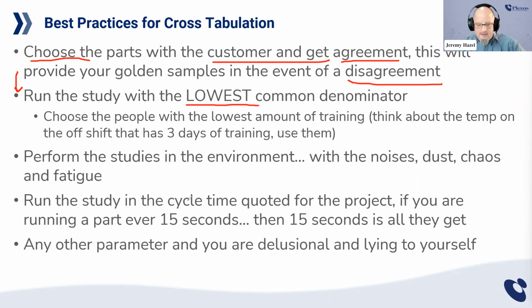The third thing, perform the studies in the exact same environment. Noise, dust, chaos, and this is a big one for me, fatigue. When I do my MSA studies, I grab my operators that will be doing it, again, with the lowest common denominator, toward the end of the shift after they are already exhausted, because that is going to give me my truest representation of what I'm getting.